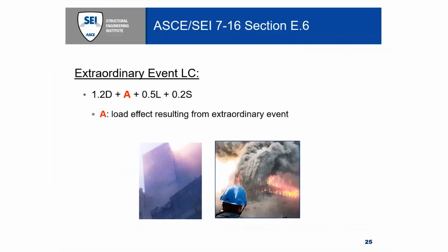When conducting a structural analysis, Section E.6 requires the designer to use the structural load combination for extraordinary events, which is appropriate for an uncontrolled fire. So that would be the 1.2 dead load plus 1.5 live plus 0.2 snow, and the A is the load effect resulting from the extraordinary event.